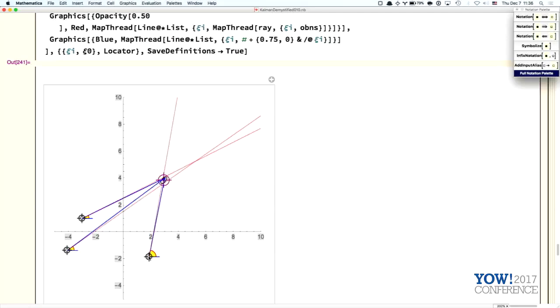The little stations down at the bottom are taking nothing but angular data. They're looking at the spacecraft that you're trying to track, which is in the center of the crosshairs, and you see they're jumping around because there's noise in the system. So all I'm taking are angles, and I'm trying to estimate a position. This is the recurring theme in Kalman filtering. You have some data, and you want something else, which is hidden state variables. So from noisy angles, I want the position of the spacecraft.